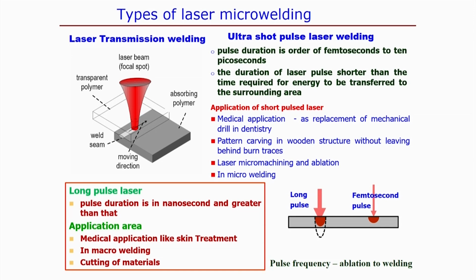The pulse duration and the finite time of heat transfer, or energy transfer, within the metal are comparable. Then there is an effect of delay, that means there is some delay in transmitting the heat flux that needs to be considered.